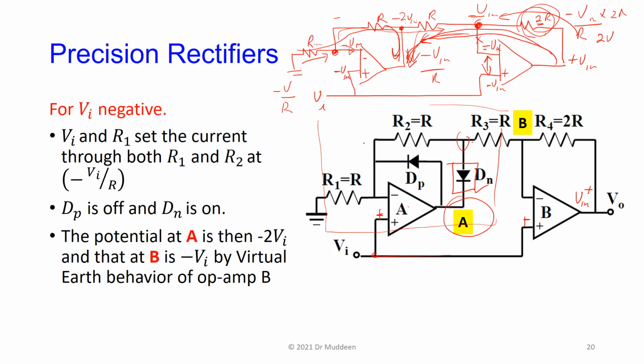You could draw it out again. If you were to draw it out from here, then this connection here doesn't exist, right? So if that connection doesn't exist, then you could see that the rest of the circuit, you have a ground here, right? This circuit is disconnected so that you basically could ignore the whole amplifier behavior on that side, and then just look at it as though you have two connected to input B, but this side is grounded.